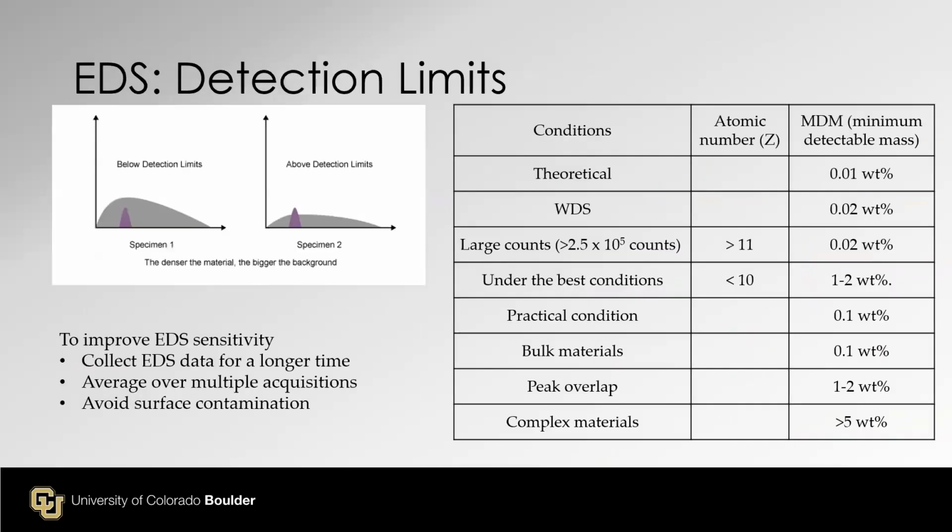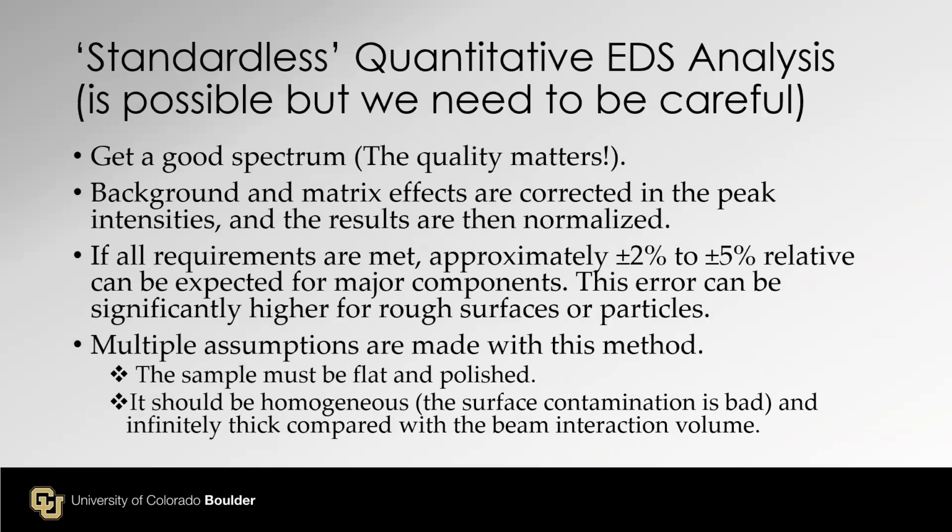One thing I want to say. Standardless quantitative EDS analysis is possible, but you have to be careful, okay? We are assuming, the same as in XPS quantitative analysis, that we have a uniform, locally homogeneous structure over a sampling volume of 1 micrometer or a few micrometers.